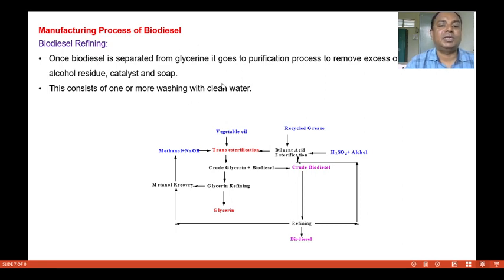Even glycerol becomes soluble in the water, and therefore it should be treated with clean water so that all of this content which is soluble in water can be separated. Biodiesel is not at all soluble in water, and therefore these get separated on the basis of different phases when biodiesel is mixed with water.